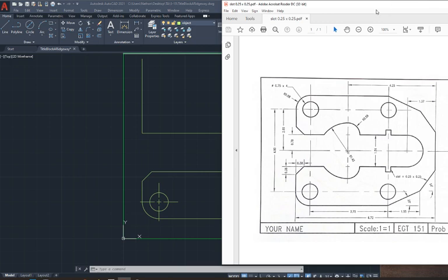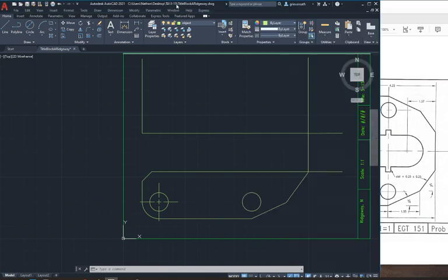So, for the rest of our drawing, it seems we only have a few simple things. We have a cutout here, we have notch cutouts, and then we have this odd heart-shaped kind of cutout here. So, to work with most of these, it looks like we will need a center line. Let's go ahead and toss that one back in there. So, I'll click anywhere on this line, turn ortho on, it goes straight down. And then I can trim this.